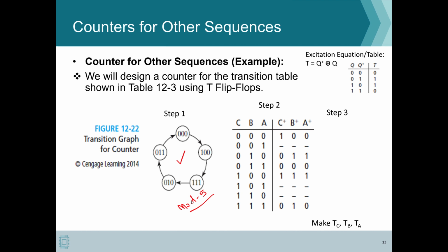So what do we do? There are a couple of things that you can do here, and this is part of your optimization. Even though we have these 5 states, for your K-map you also require your table to be completely represented. Which means these states, which are 0 0 1, 1 0 1, and 1 1 0, are part of your design. If we want to optimize it, then you can assume that you really don't care about what your next state is.